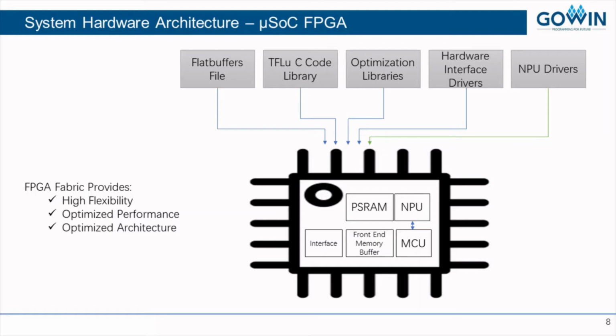Second, you can just interface to a lot more things, or different interfaces that you may not be able to do on the microprocessors. So multiple cameras, multiple CSI2 cameras, MIPI CSI2 cameras. You could add a display for displaying your content. You can add as many I2S microphones as you want.